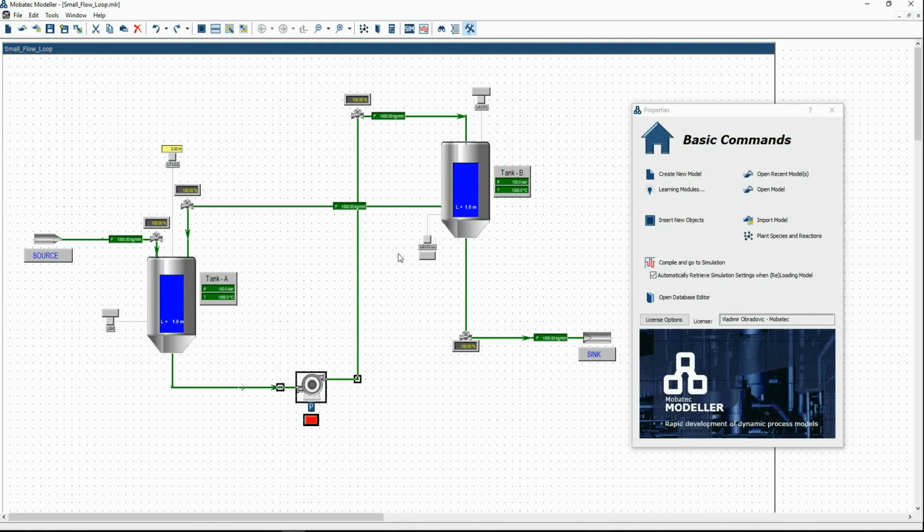And if we want to reuse the flow display of the line from the pump and the valve display, the same line, we have to select them as well, as they are also separate objects than the connection line. So hold your Control button on the keyboard and select both of them. Do right mouse click on the selection and choose Copy.